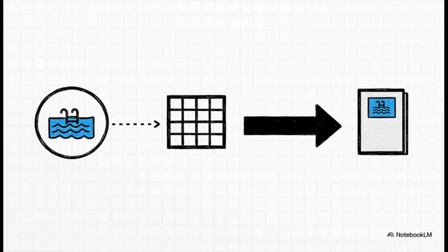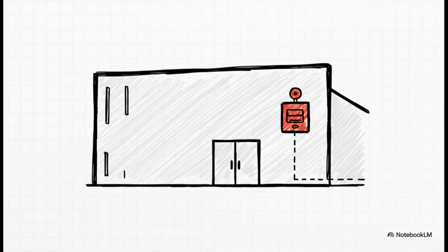It's so important to recognize that the NEC manages more than just power distribution. It manages energy limits. Meaning we separate low power control and communications wiring from standard power wiring, because the danger isn't necessarily a massive shock, but the uncontrolled flow of energy that can start a fire or disable a life safety system. Right, so why do they need different wiring methods?